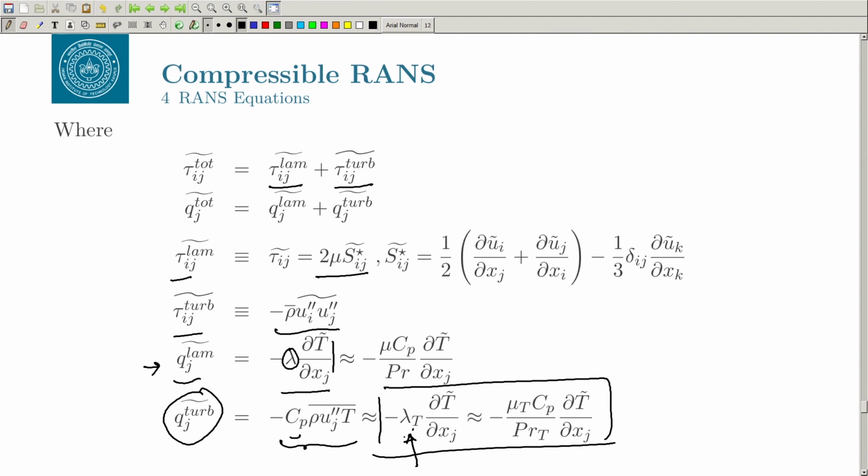Remember the Prandtl number we had discussed earlier, mu Cp by lambda. So this lambda becomes mu Cp by Pr, and for a gas, for example air, Pr is equal to 0.7 or 0.71, and you know Cp, you know viscosity, so you can calculate the conductivity.